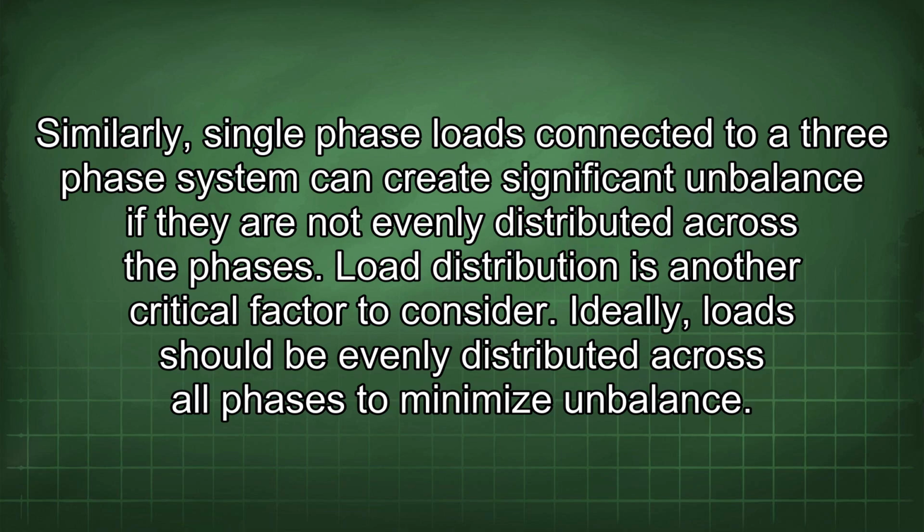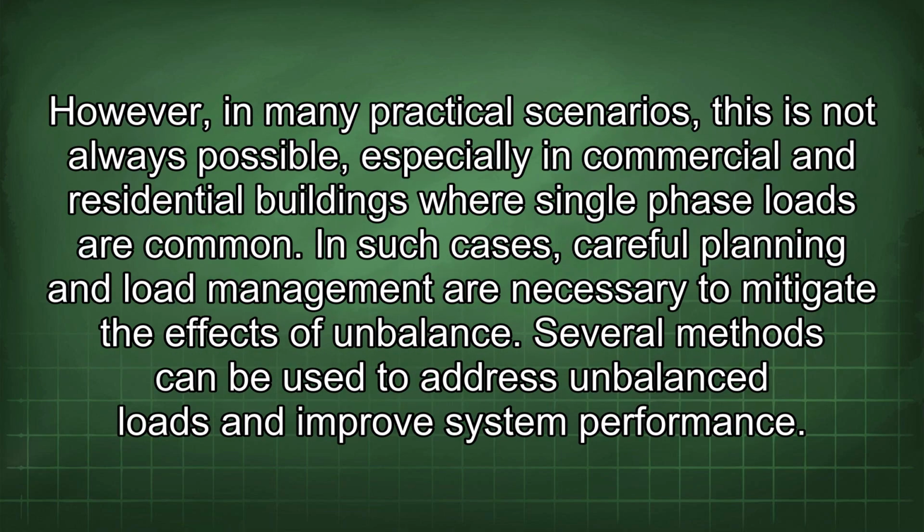Ideally, loads should be evenly distributed across all phases to minimize imbalance. However, in many practical scenarios, this is not always possible, especially in commercial and residential buildings where single-phase loads are common. In such cases, careful planning and load management are necessary to mitigate the effects of unbalance.